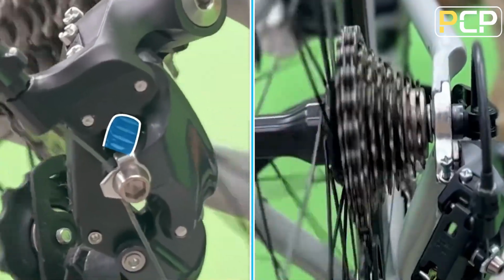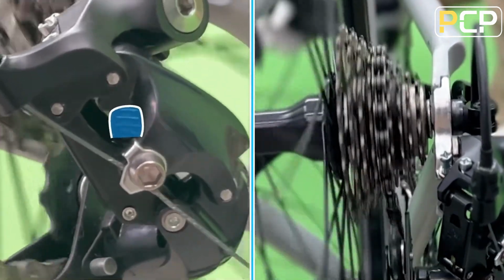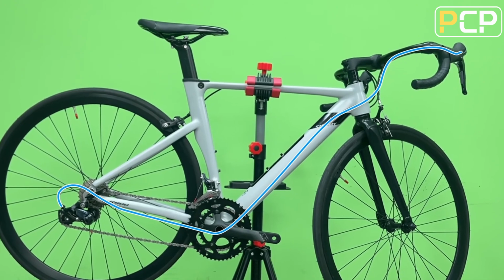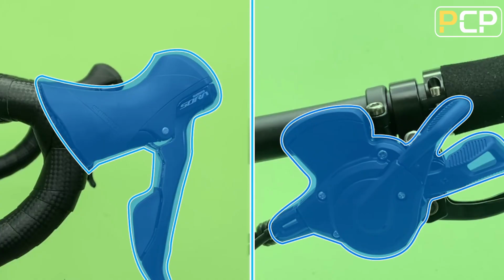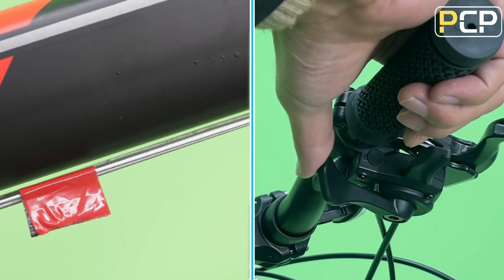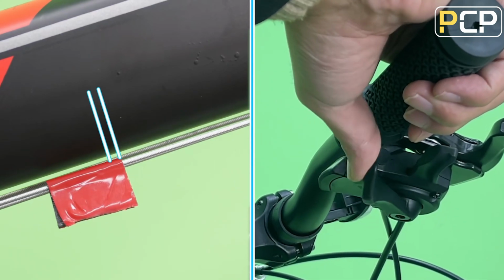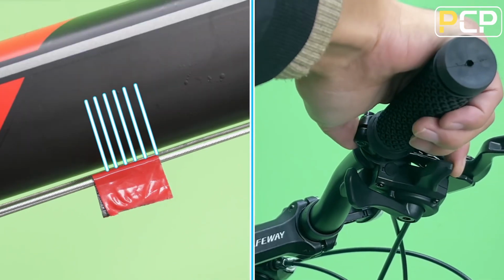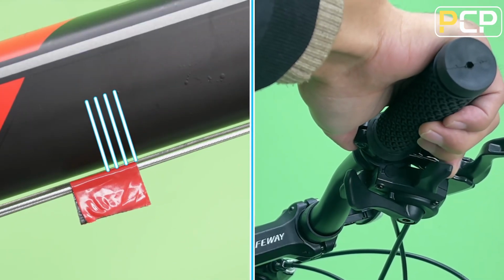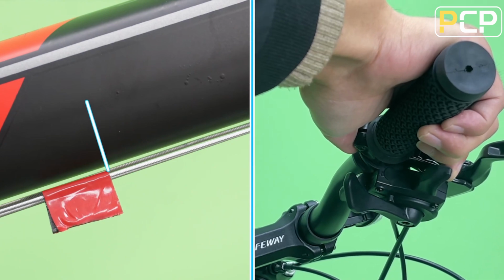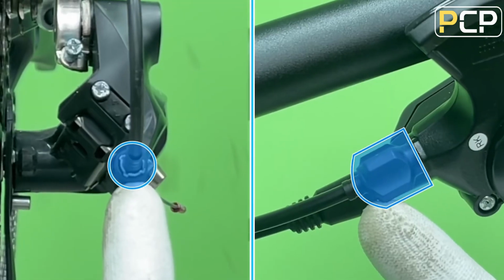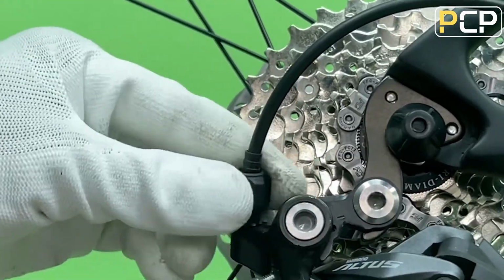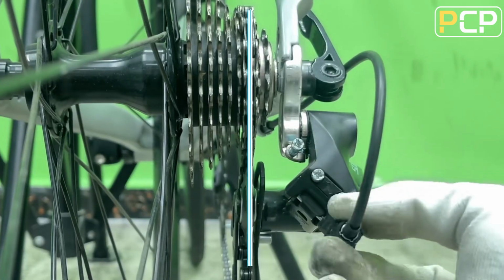Low normal rear derailleurs return the chain to the largest sprocket on the cassette when no cable tension is applied. While this was once a common design for rear derailleurs, it is relatively uncommon today. In mountain biking and off-road cycling, the most critical gear changes occur on uphill sections, where riders must cope with obstacles and difficult turns while pedaling under heavy load. This derailleur type provides an advantage over high normal derailleurs because gear changes to lower gears occur in the direction of the loaded spring, making these shifts easier during high-load pedaling.